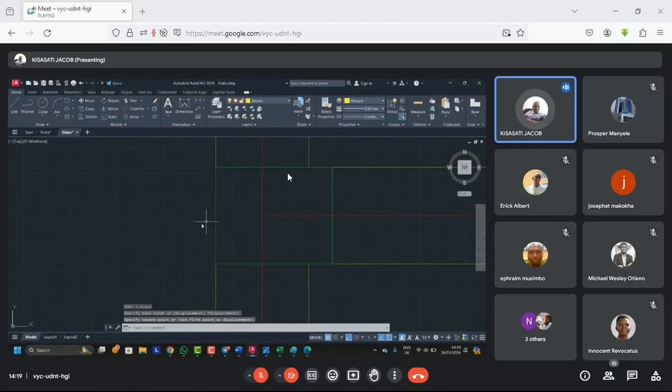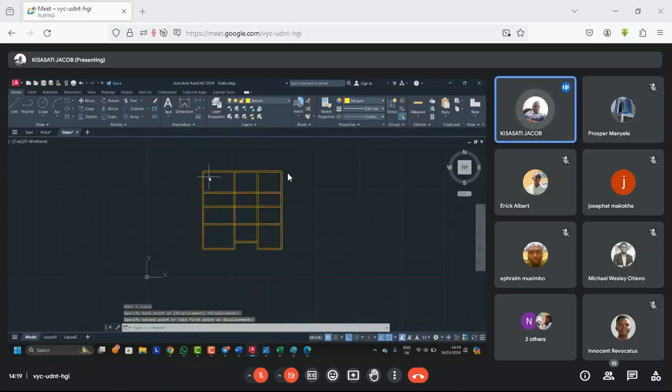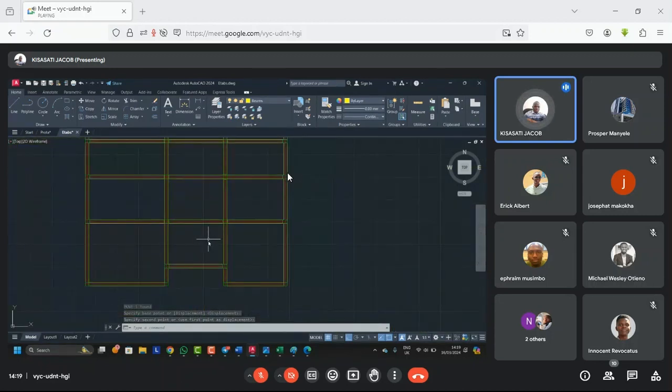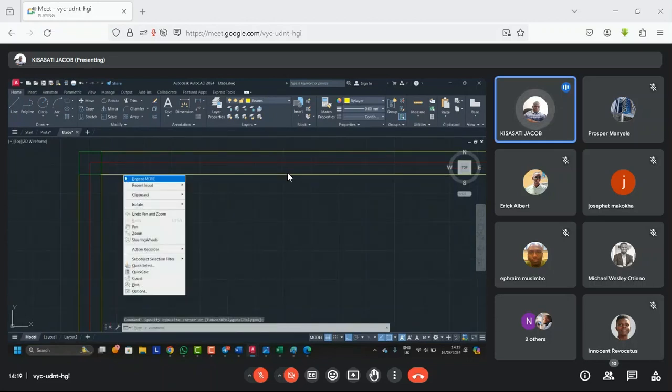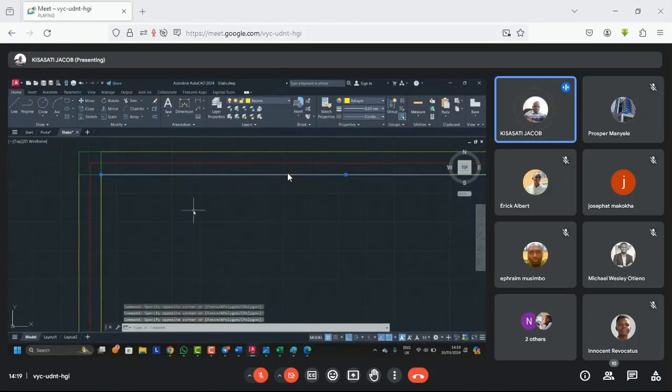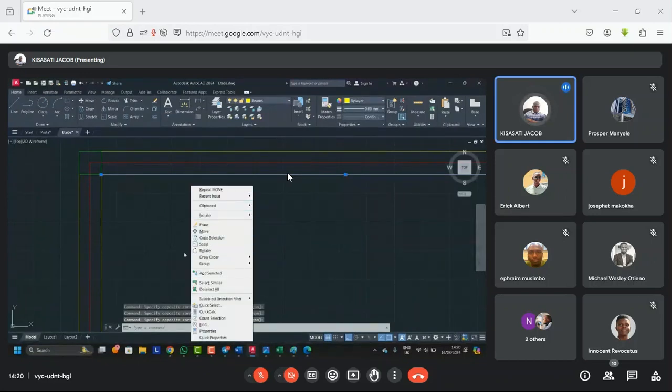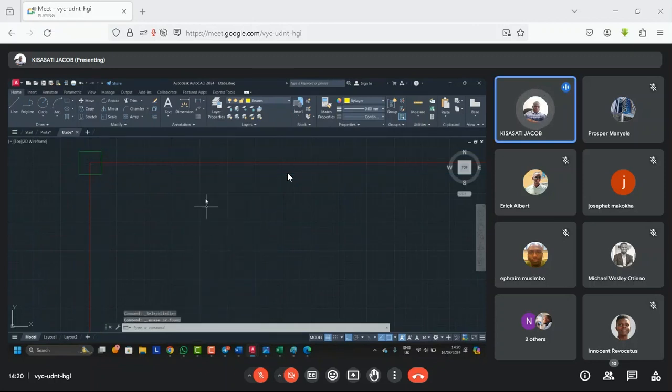Now, please pay attention to what we are going to do, because this is now what you call coming up with the layout. So in ETABS, you can actually delete this, or we can just leave them. It depends on how we are going to monitor them, but let's just delete them. I'll select similar, then I'll delete. So the only thing that we have is the columns and the grid lines. These grid lines are the ones that we are going to use to create the beams.